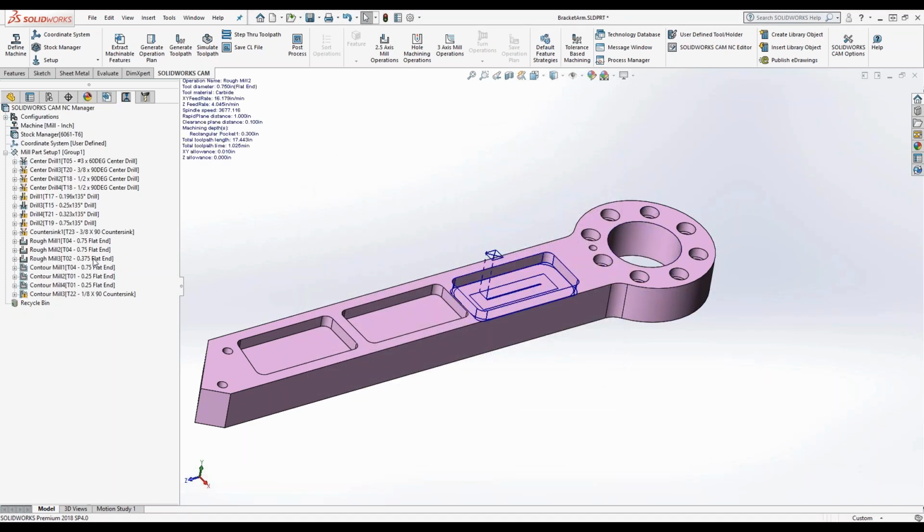We even have a tool change here between this rough mill and this rough mill before it goes into this contour mill. Since this rough milling doesn't affect that contour milling, I can even drag that up manually. So now my 3/4 end mill is going to get all of its use before we switch out to a different end mill, right? That can help maximize our tool time and cut down on extra tool changes and things like that.